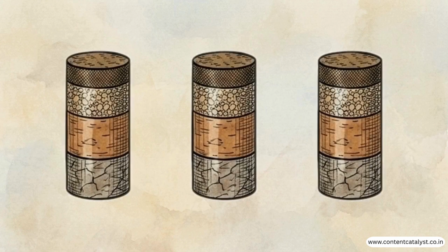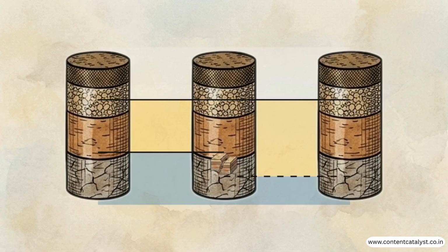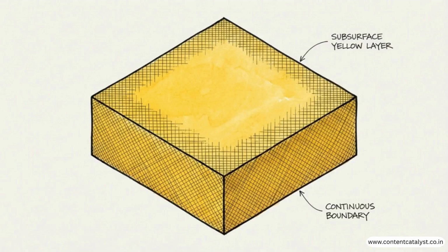We map boundaries by drawing lines between matching material interfaces, connecting fill to fill to enclose the space between boreholes. Select the correct line type carefully. Mapping a structural fault or isolated lens requires different settings than a continuous boundary. Drawing these interfaces translates your scattered data points into a continuous, predictive map of the ground conditions.